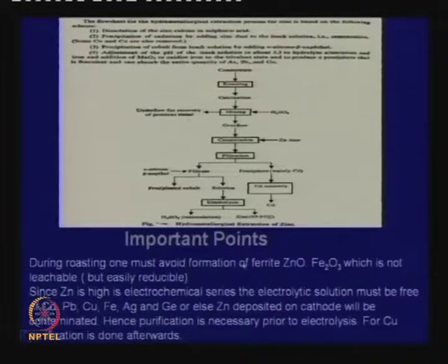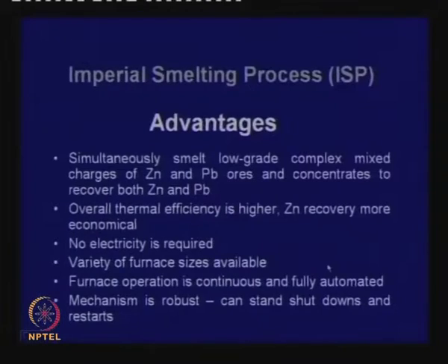There is another important point, that when we are roasting zinc sulphide concentrate, one has to avoid formation of zinc ferrite, which cannot be leached. So, in extractive metallurgy of zinc, the formation of zinc ferrite is a very important subject.